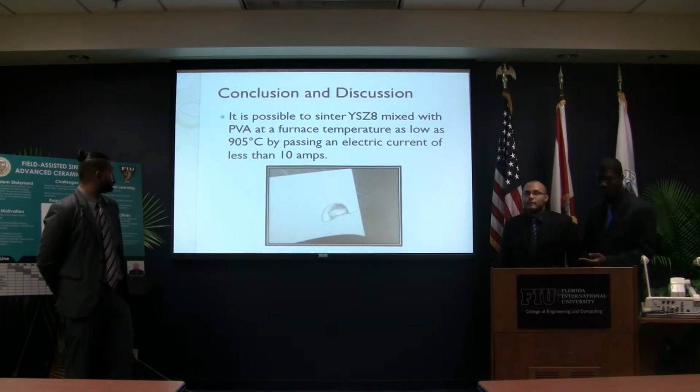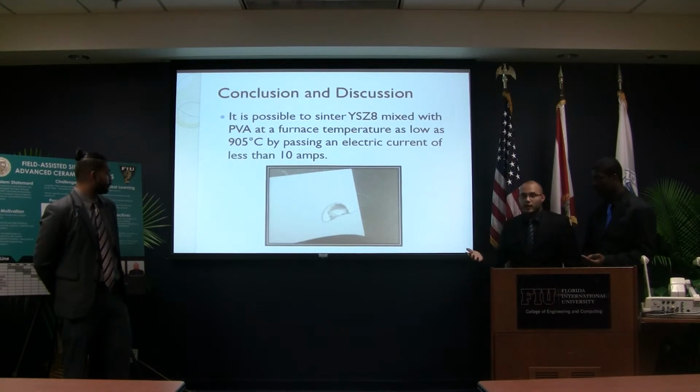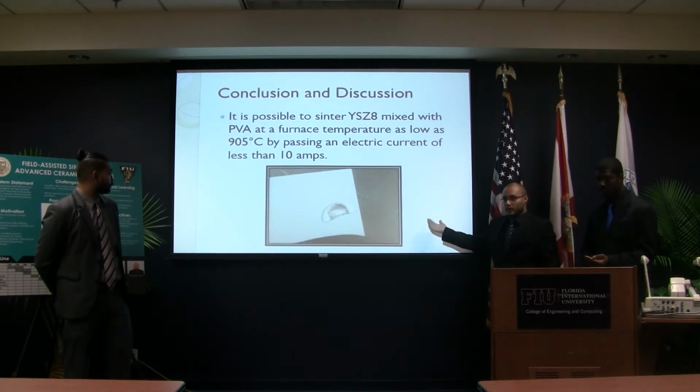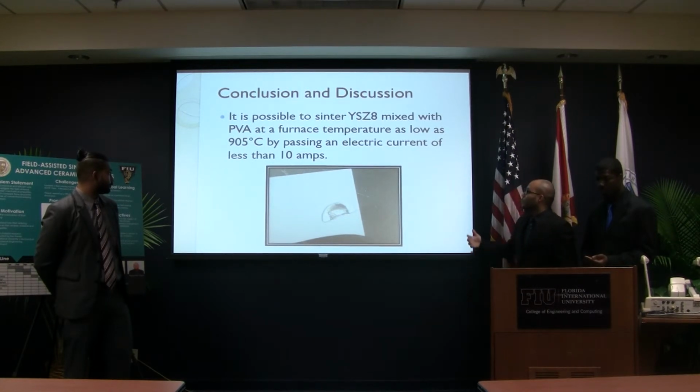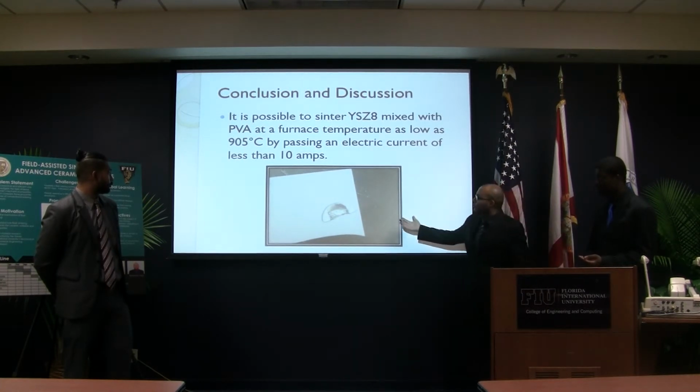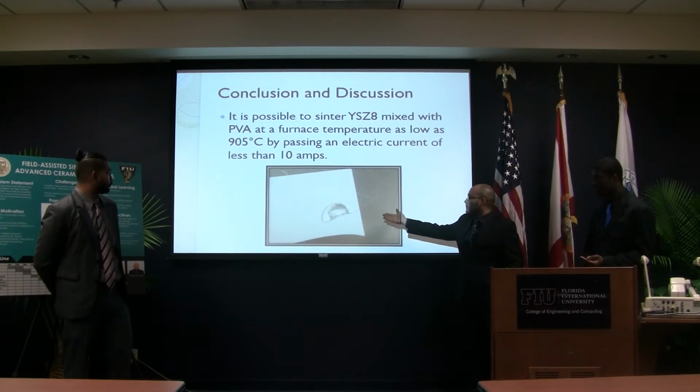We used that design to run one trial because of the amount of time it takes to run each experiment. It's about 4 hours of constant heating, an hour of soaking at the constant temperature of the furnace, and then cooling it down in 4 hours. We were only able to do one trial using our future development prototype, and after we took out the sample, we saw some discoloration, which means that something actually did happen to the sample.